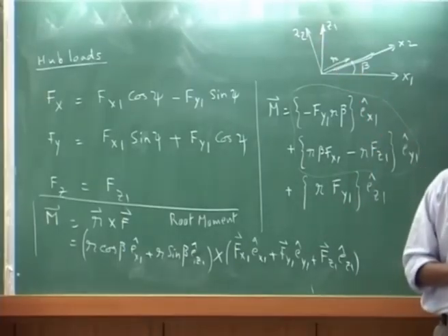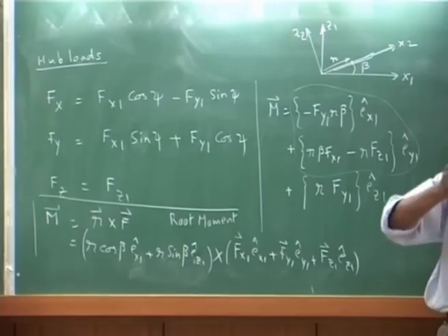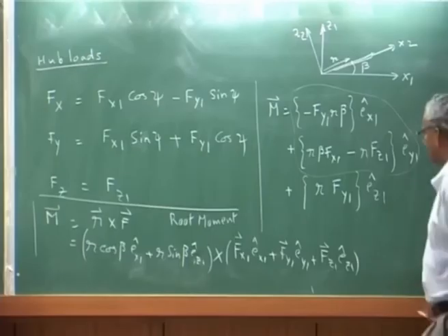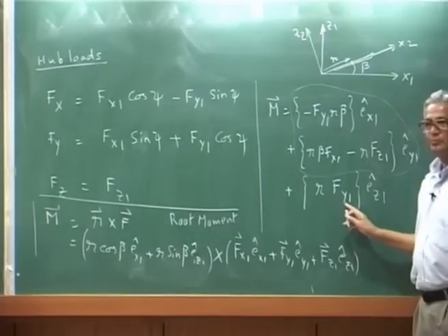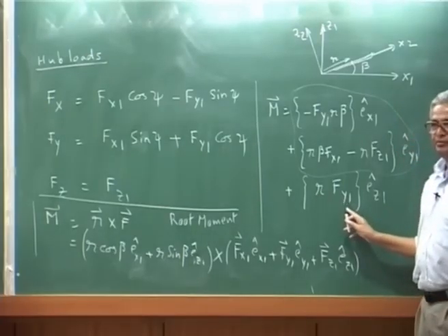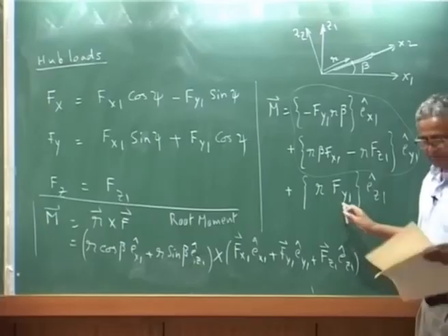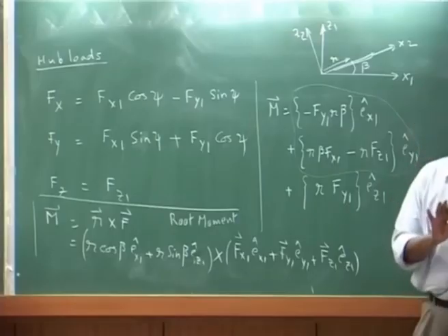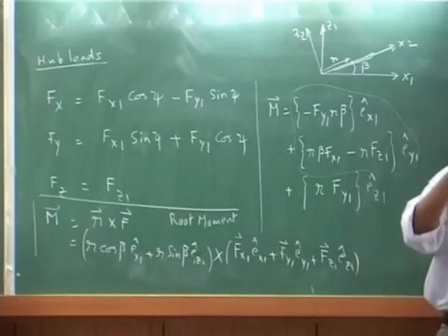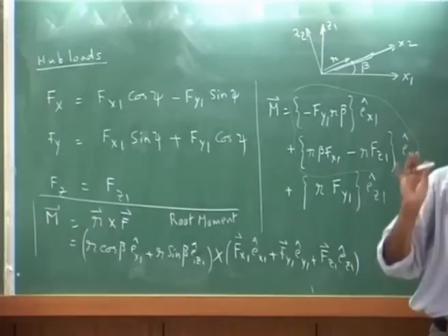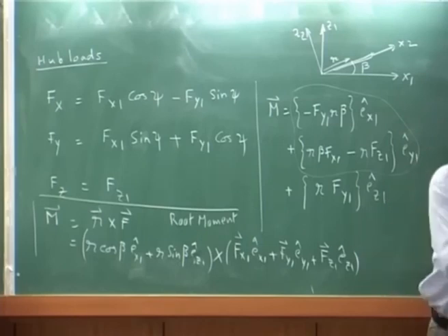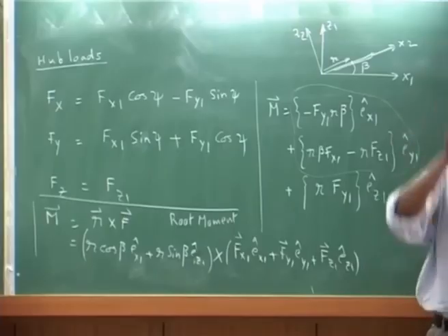So, my torque acting on the shaft is basically Rfy1, and you can take this quantity, calculate torque at the hub due to all the blades, because all the blades will sum it up. There is no cosine psi sin psi, because all of them are only in the z direction.